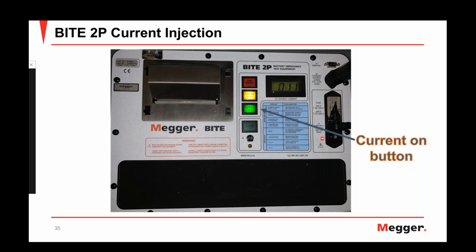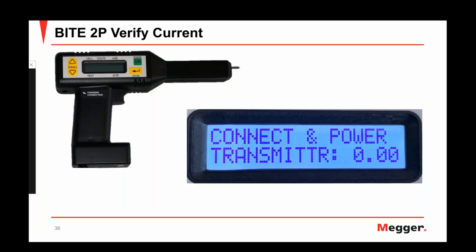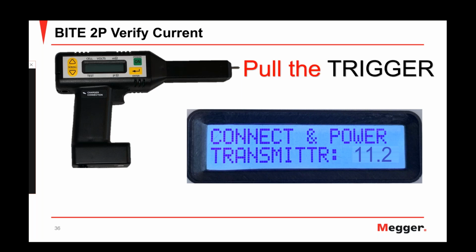The next step is to go back to our receiver and refer to the screen, and look for a current value. We can see here that we have 11.2 amps registering on the receiver unit, and the current transmitter says that we're outputting 11 amps. This is an acceptable reading, and we can pull the trigger on the unit to record that value, and move on to taking our impedance measurements.